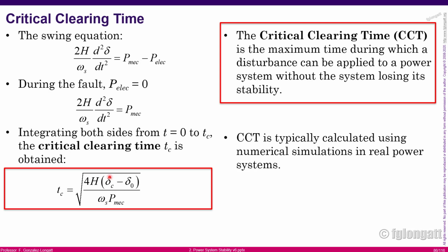What is really important is that all those relays, including all those discrimination times, must be below the critical clearing time. What I'm trying to say is the critical clearing time is important from the protection point of view because all your protection must work and must trip for a short circuit before the critical clearing time. All protections must trip and work before the critical clearing time, because if you reach the critical clearing time, the system will be unstable. There is no reason for protection if those protections will work after the critical clearing time, okay? This is the first conclusion from the protection point of view.